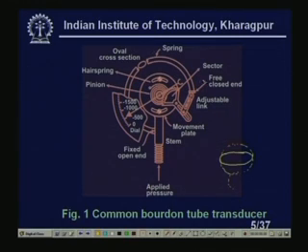Again I am telling, if I apply a pressure higher than the atmospheric pressure, this tip will go outside. If it goes outside, this sector will move in this direction. If it moves in this direction, the gear to which the needle or pointer is connected will move in these directions, right? So I will get a change of pressure.